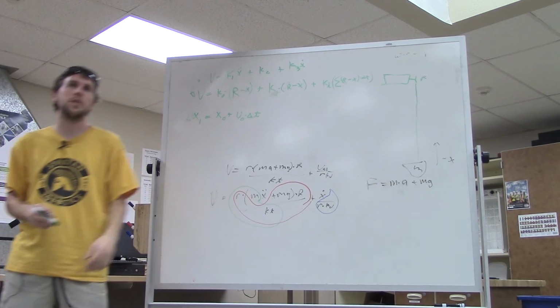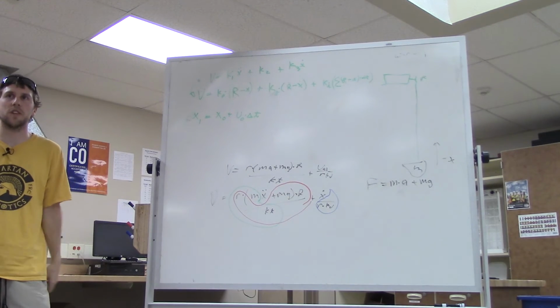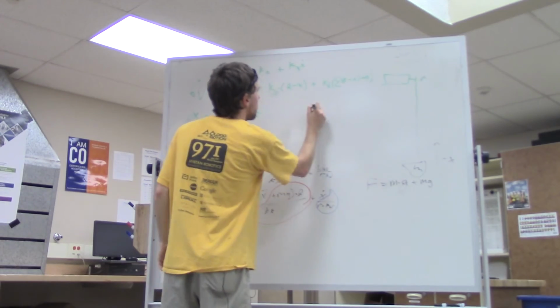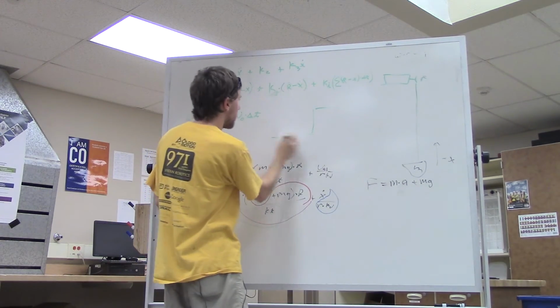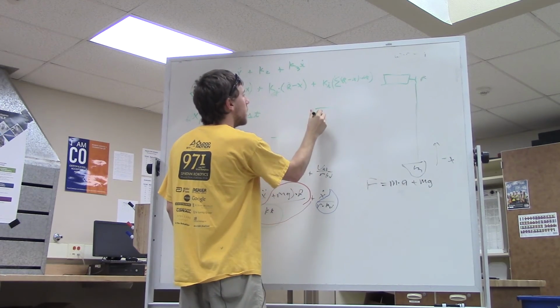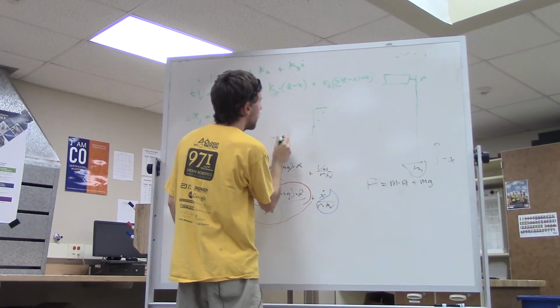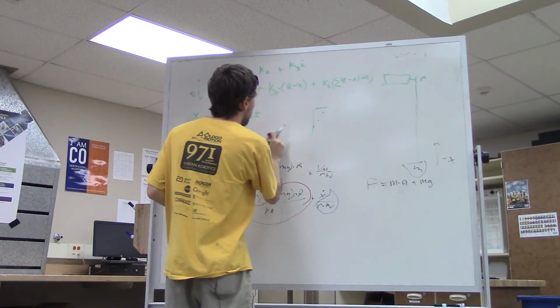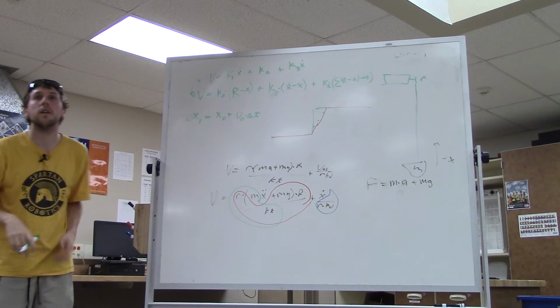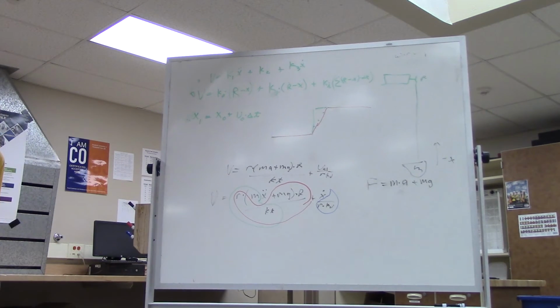We can talk about the frequency response of that. What does that do to your signal? That will actually delay your signal. Because if we feed a step input in and then look at the response, the first time step it's going to be a quarter, then a half, 2/3, and then it's going to be there. So we're going to get a ramp. Yep, exactly. So the filters modify your signal, and depending on what you want, they'll slow it down while reducing noise, or there's a bunch of different types of them.